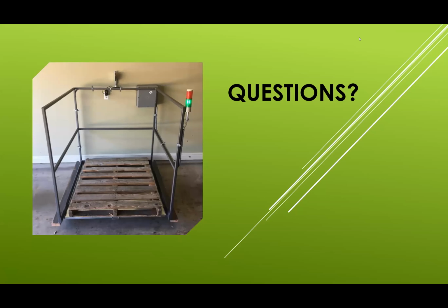As a matter of fact, if we were to add one dimension to this, and it would be a vibratory shake, we are actually considering looking at this design to add to our current tote dump over what we call the overflow area. And that could really complete this design to where we feel there's a really good application for us here in the plant. Meaning a side-to-side movement, as the students explained, that mounding of the French fries as they come into the tote. So we would work on it, but certainly the team likes the load cell, the weigh cell, and the combination of the visual indicator that we would then add to our program for the tote, the automated.